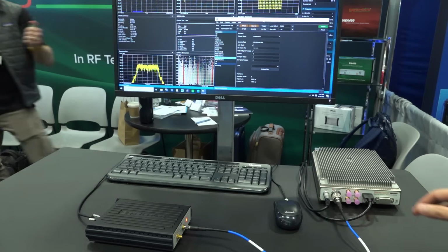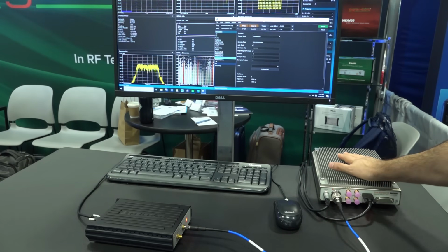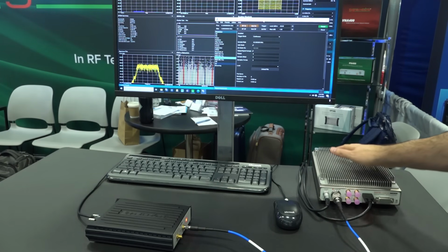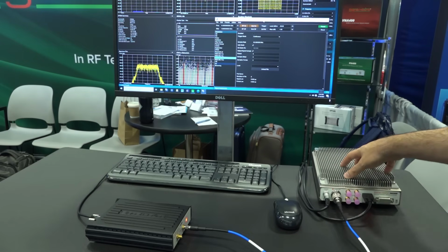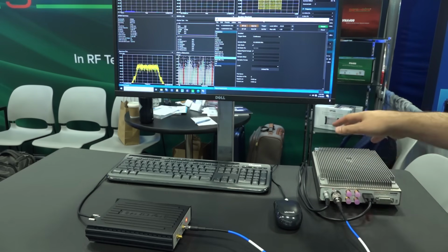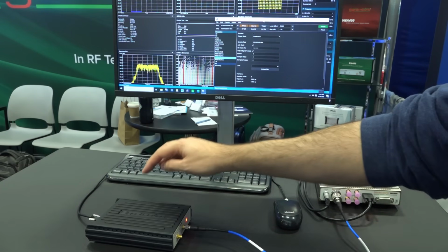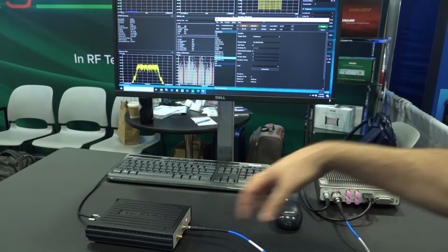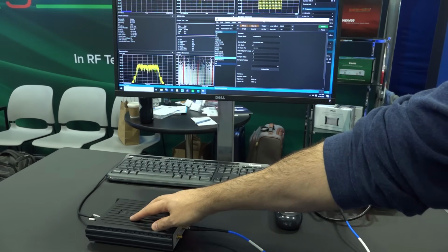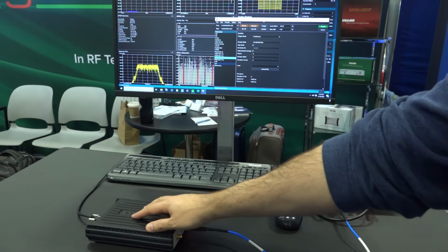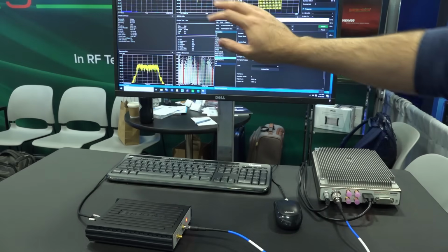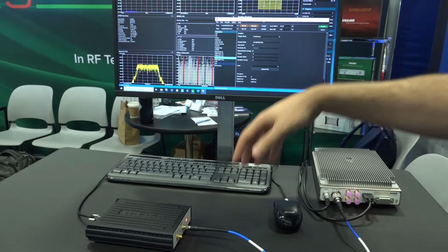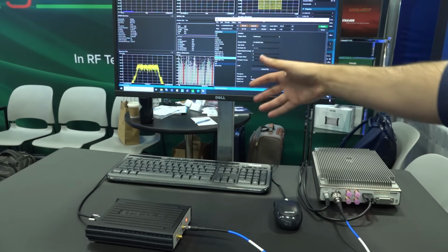So if you've been watching the channel, you definitely have seen the extensive review of the SM200C and SM435C. This is a 20 gigahertz real-time spectrum analyzer. And now they also have a 20 gigahertz vector signal generator that pairs with it really nicely, with 40 megahertz of arbitrary waveform bandwidth that you can apply anywhere on the band, with free software that sits on top of it. You can generate all kinds of different standards and modulations and everything.